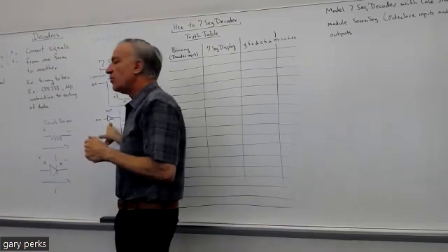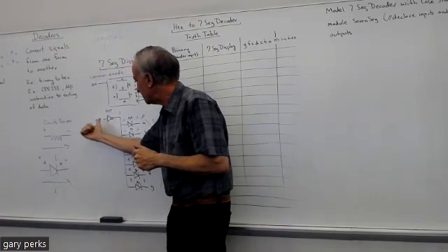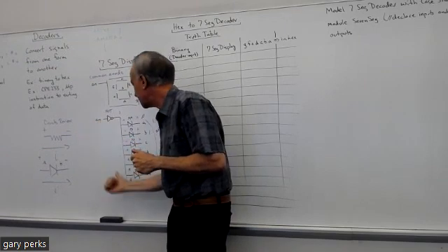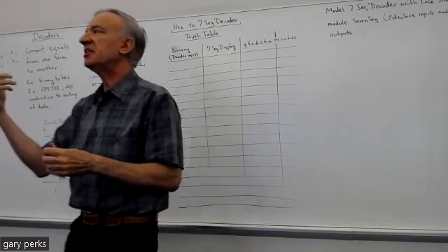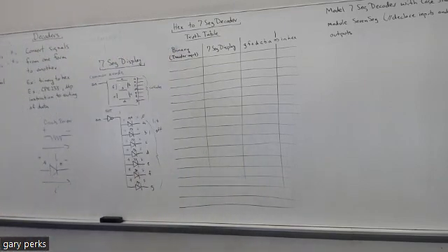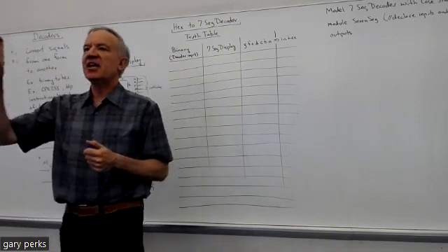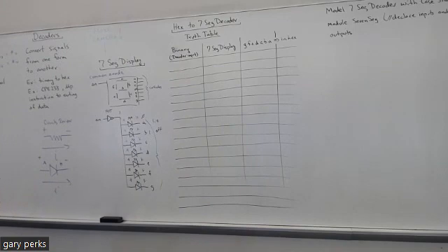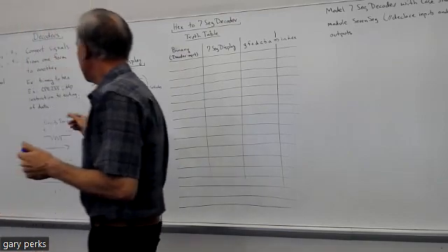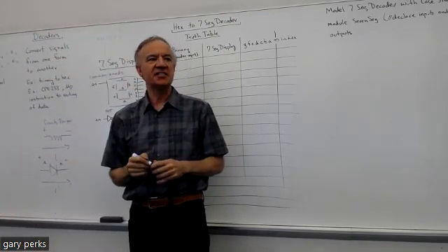The reason they put an inverter here, instead of just having the anode go directly to the connection, is that they want to get some current gain. If the transistor wasn't here, there wouldn't be enough current for the LEDs to be bright enough. So the NOT gate is there just to get better illumination of the LEDs.